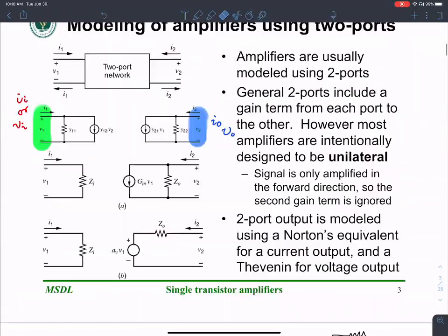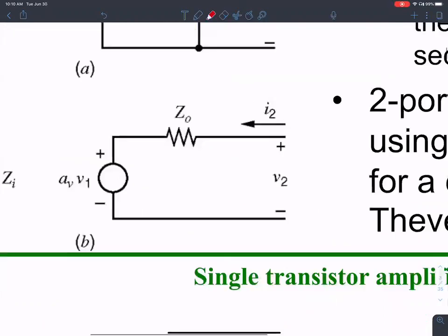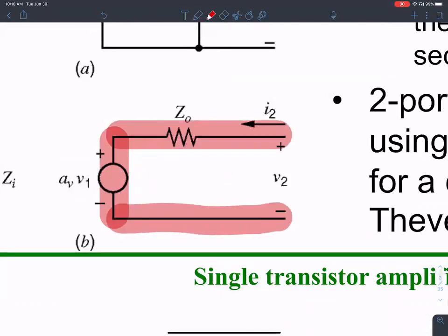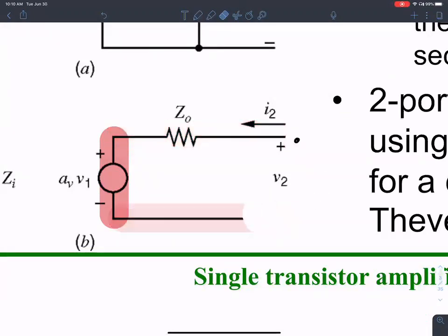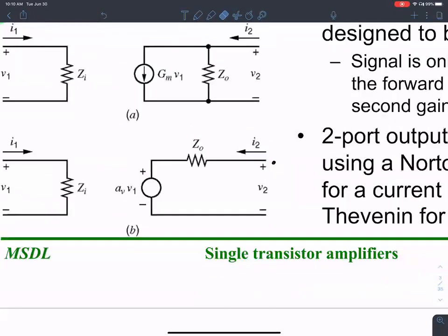Similarly, a voltage source with a series resistance is the definition of a Thevenin equivalent. When you're looking at the open circuit voltage here, it has a set voltage that you'll see across these two terminals. So this is the standard form of representing voltage and current sources.